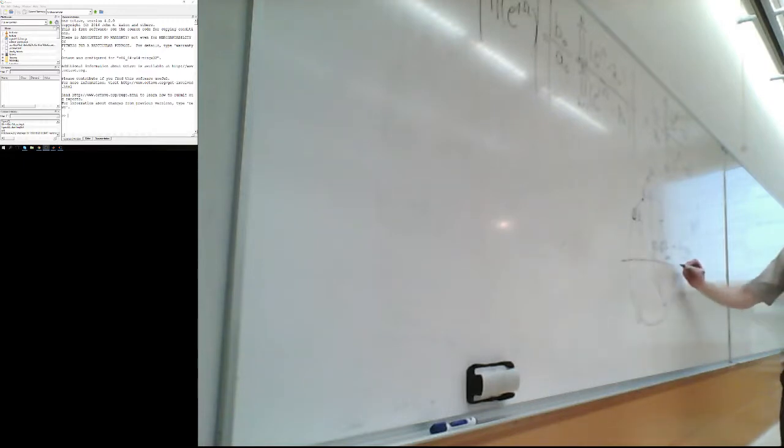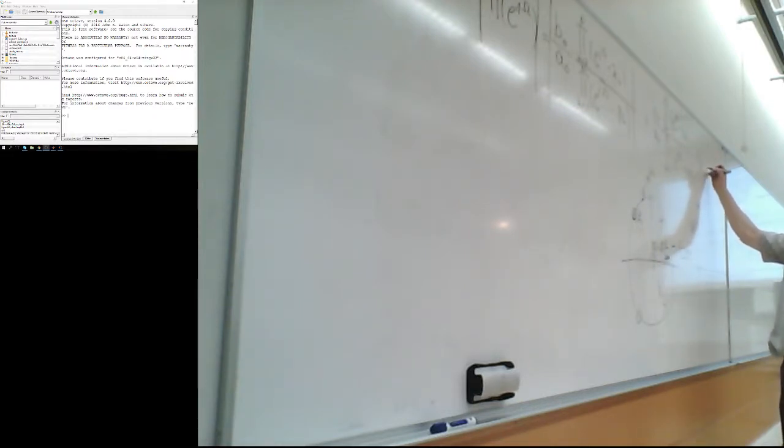So if we have, for example, this point, then omega is 0, which is the physical frequency is 0. So at this point, we can calculate this one, basically just the scaling factor. Then there's a product of e to the j omega minus z1 times e to the j omega minus z2 divided by e to the j omega minus pole 1 times e to the j omega minus pole 2.